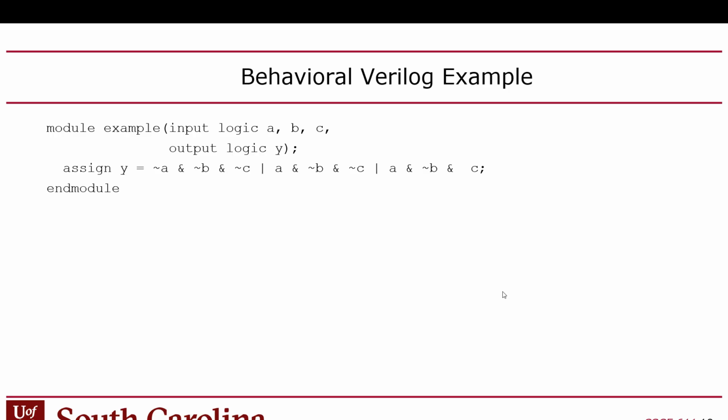So basically, if you have multiple inputs, that's a shortcut you can use. You don't have to do it. You could say input logic A, comma, input logic B, comma, input logic C. As a matter of fact, if you are serious about your code being beautiful and readable, you wouldn't even put those on one line. You would do what my former student Charles would do, and you would put every input and every output on a separate line with line breaks, and you'd have them lined up in a column, real nice, indented, right? But this is a quick and dirty thing where I just say input logic A, B, C.